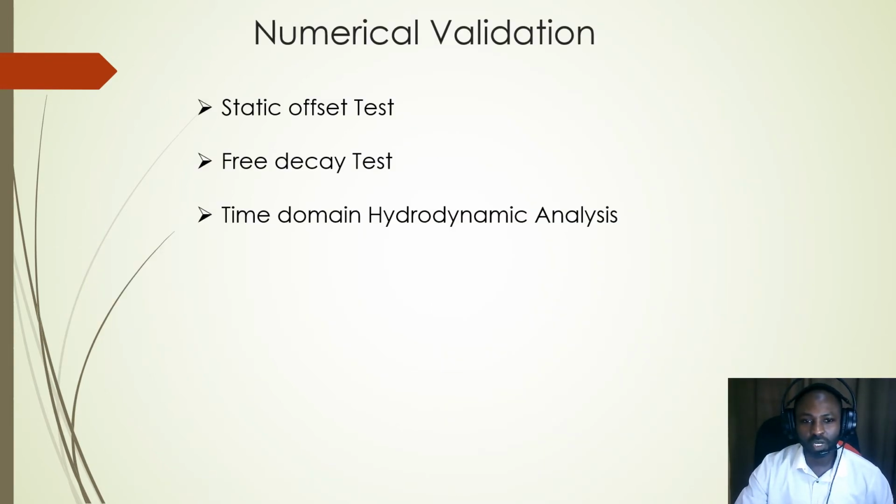For the numerical simulation, we conducted 3 tests, which include the static offset test, the free decay test, and the time domain analysis test. The static offset test is majorly conducted to determine the restoring force of the mooring line, because that gives the idea of the ability of the mooring system to resist excursion of the FPSO under environmental loading.